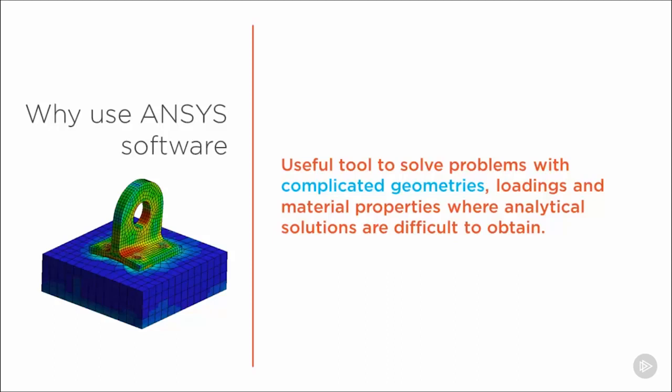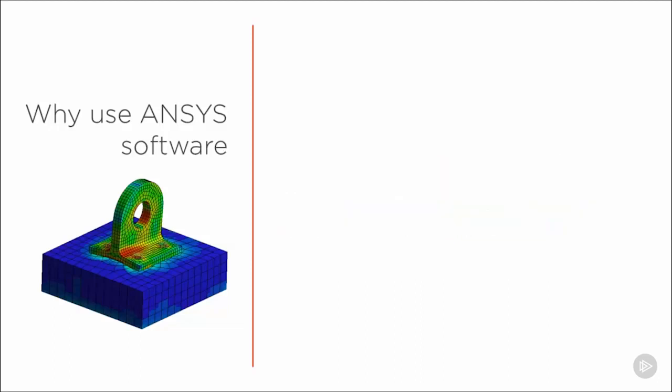In our problem, for example, we have a lifting lug design with a bolted connection and multiple fillet radiuses and somewhat complex geometries. So let's say we want to solve the stress in every area of the system and find the location of maximum stress. It would be possible, however, it would be much more time-consuming and less accurate when compared to the finite element method. So we also use Ansys to ensure the design safety of our equipment.